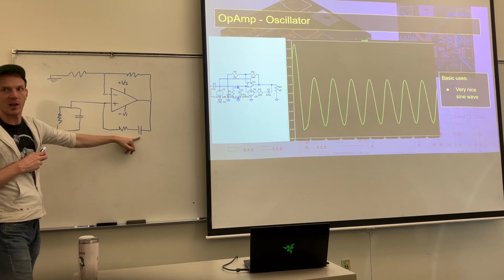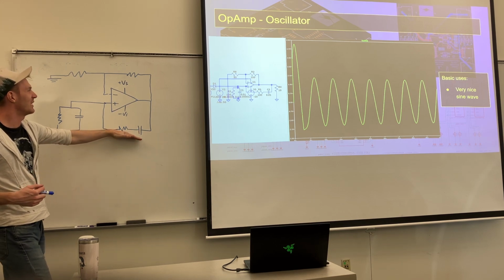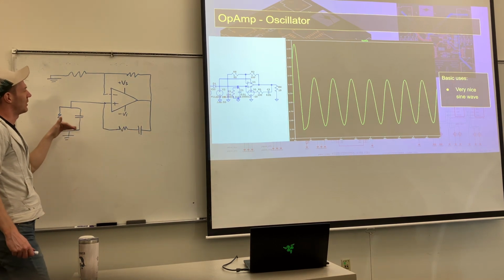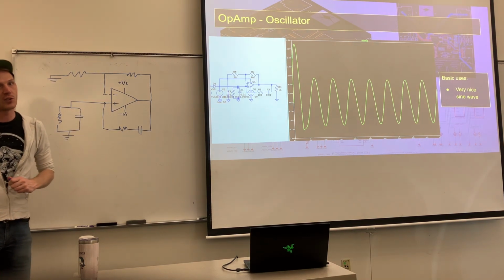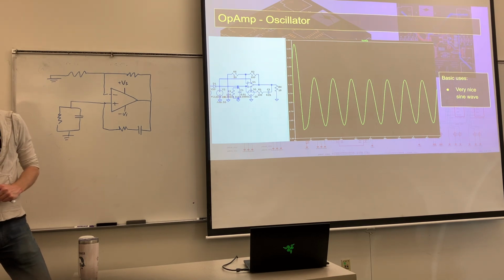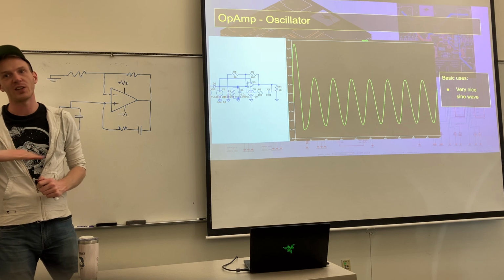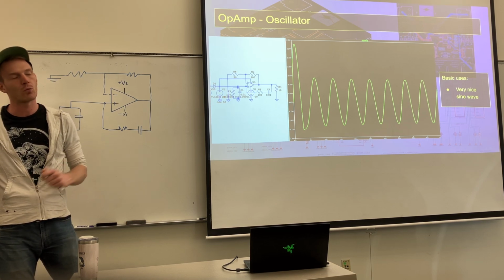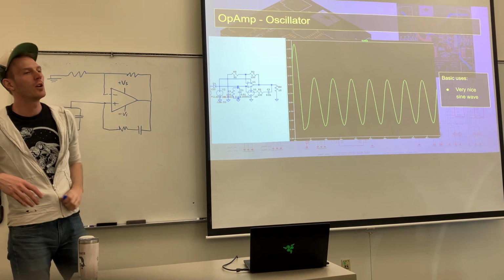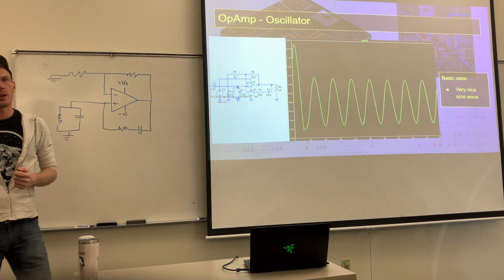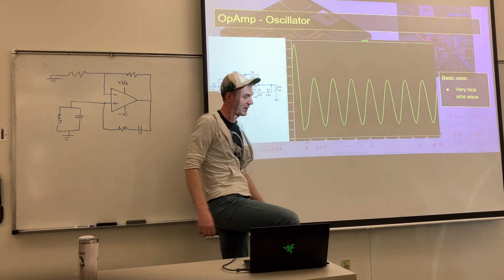A lot of inductors and capacitors is used for timing and wave shaping. And so when you see inductors and capacitors being used in weird ways, you should think all right, this is probably being used to either delay a signal, or if you're dealing with AC, then passing AC through one of these will either completely get rid of it if it's too high a frequency, or completely get rid of it if it's too low a frequency. Or it will phase shift it by half a pi or pi, depending on what you're doing. And that's dependent on the angular frequency.